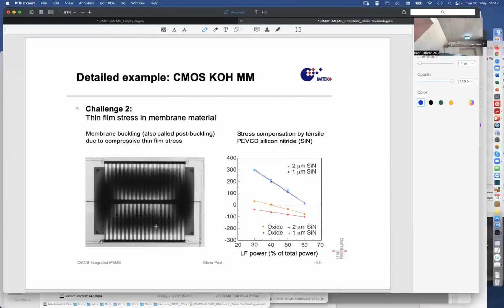And you do that by covering the membrane with silicon nitride passivation that has a tensile strength. That makes like a drum, that wants to be flat. We put an additional drum layer to pull this flat, and the stress of this drum layer is documented here. So this says megapascal. And then there are different kinds of silicon nitride that can be deposited in a machine with one parameter called the low frequency power.